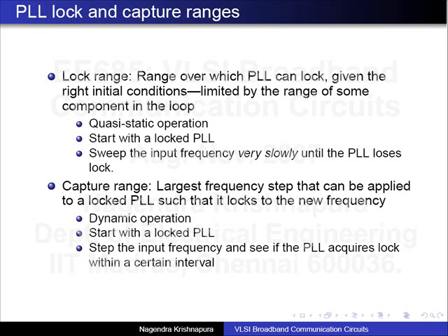Now the capture range is a dynamic phenomenon. Let's say you start with a locked PLL and then you apply some frequency step, whether it actually locks to the new frequency or not. It may or may not do that, or it may take an extremely long time to do that. So it is a very nonlinear process, and that's what capture is all about.